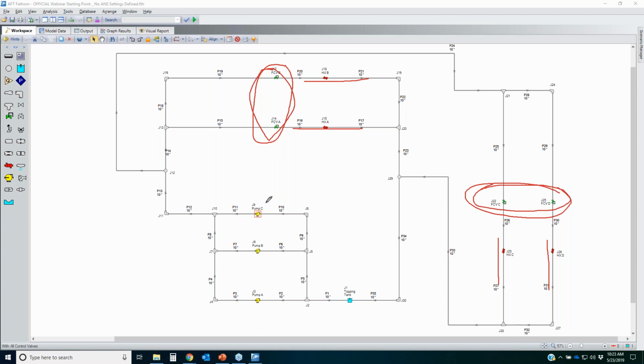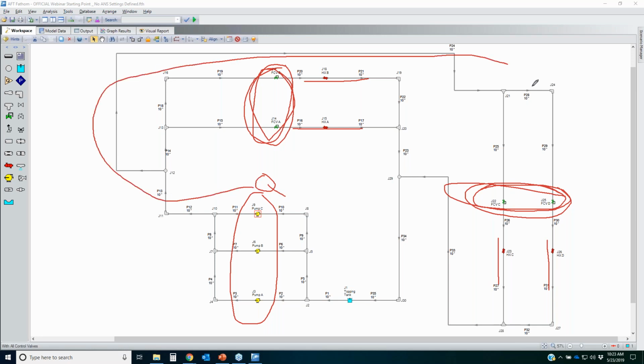But here's the thing. If you specify fixed flow rates for your pumps right here, as well as fixed flow rates for your control valves over here and here, what you have done is you have a known flow boundary right here, and then as you go around these two different loops, you have another known flow rate here, as well as a secondary known flow rate here.